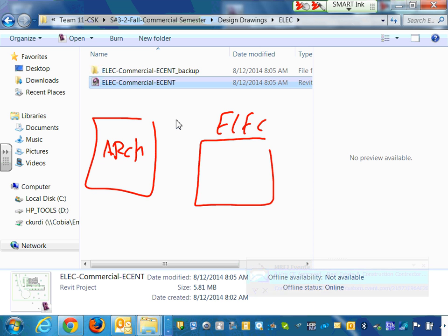And when you link it, you will see later on when we say link, I grab a copy of this and put it right in here. Now you can see the architectural inside your electrical file. That's called linking, or XREFing in CAD. In CAD, they call it XREFing. In Revit, they call it linking. So what does that mean? It means you have an identical picture of everything the architects have. When you're working right here doing your receptacles, you see exactly what the architecture project is, except you can't move a wall, delete the ceiling, or move the building.